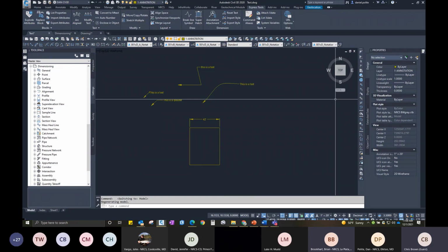And the same for the dimensions. The dimensions should all be the same size, and they should also all be the same units for the particular detail or profile that they're related to. Like if all your dimensions are in feet, you shouldn't have a mixture of feet and inches in that same detail.